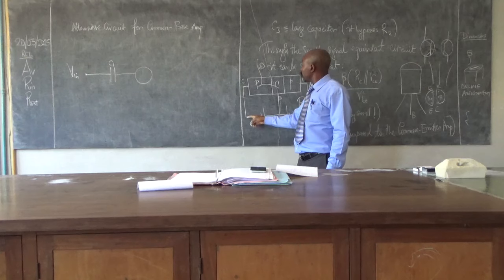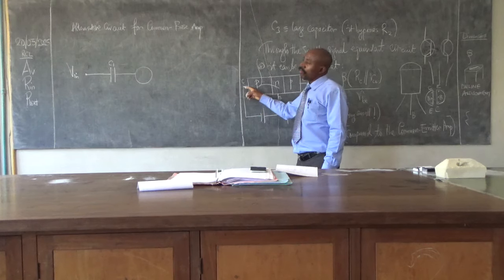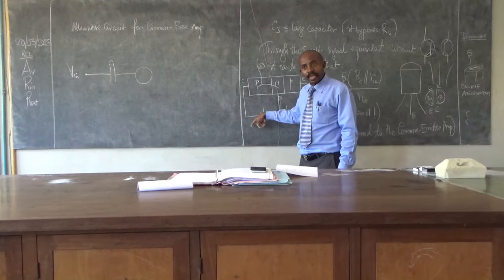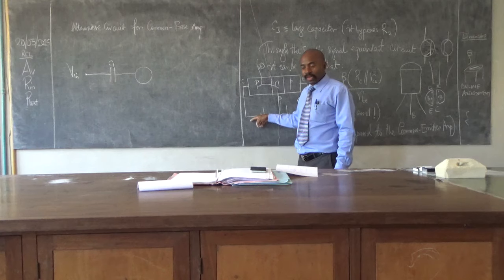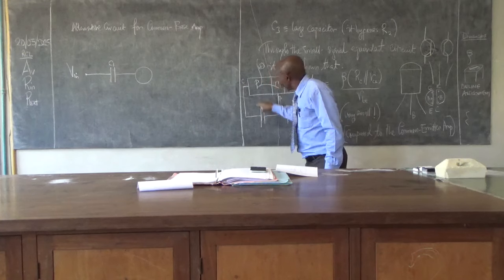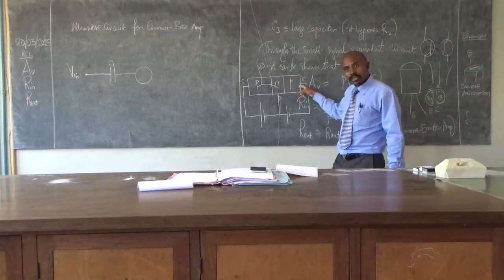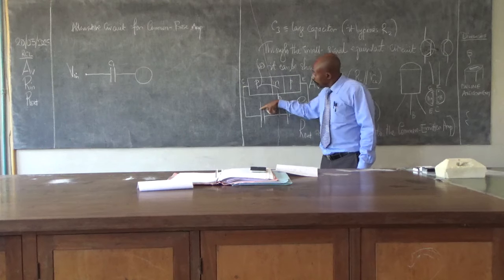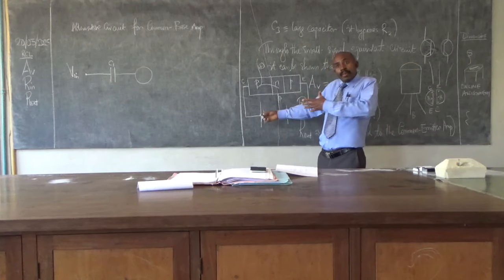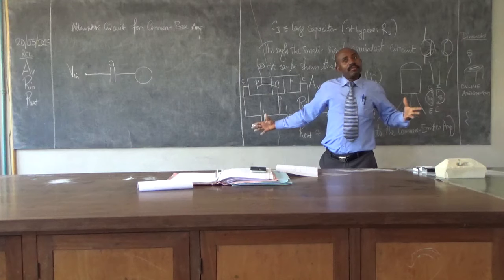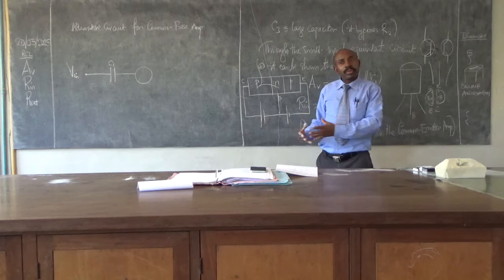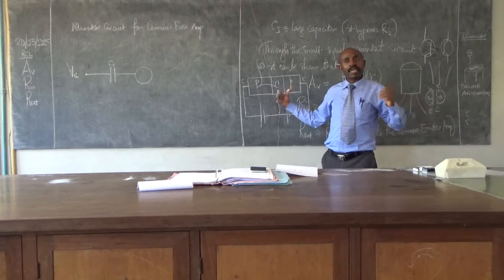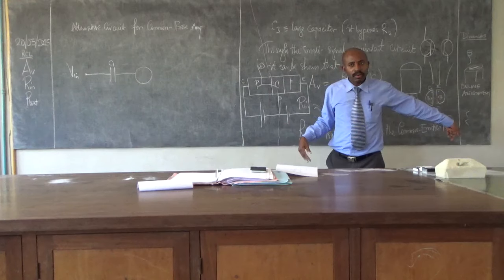When this is a negative here, that means they also have a possibility of flowing to the other side because of being attracted from this side. If you put the positive here, you make them flow across the junction because they are being repelled by these other positives. When you put negative here, they are attracted. So you are making the depletion region even bigger. So now it is resisting everything and giving the current another place to go.